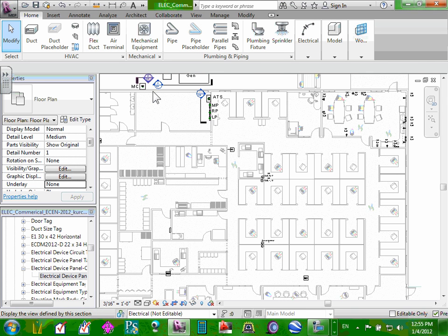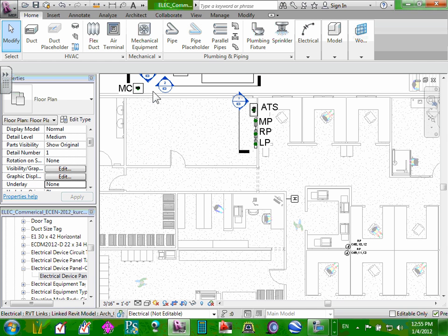Okay. Mechanical equipment. Now, the only thing we haven't touched on is lighting. Lighting is a whole different animal. We'll get to it when we reach lighting. Receptacles, guys, you should be able to spread all the receptacles all over and circuit them based on the criteria. The only thing I want to touch on right now is mechanical equipment. For mechanical equipment, you need to have a family for them. So do me a favor: go load the families for the mechanical equipment all at once. At least one of the team. Insert.